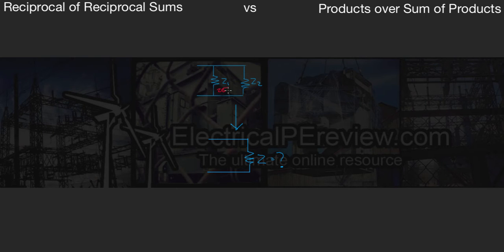Say this is a 25 kiloohm resistor, and this is a 25 kiloohm resistor. Anytime you've got just 2 in parallel and they're the same value, you can take that resistor and halve it. So this equivalent resistance would be 12.5 kiloohms. And of course, to prove that it works, we're going to do it products over sum real quick. We're going to say 25 kiloohms times 25 kiloohms divided by the sum of the 2, which is 50 kiloohms, equals